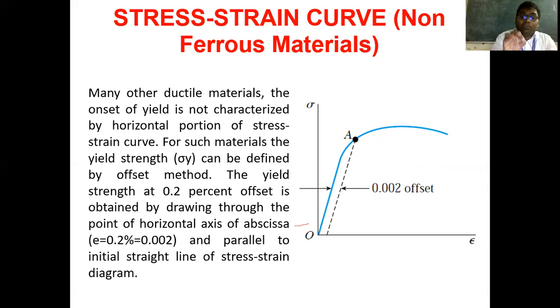All the designs we make for any kind of machinery or element consider the yield stress, so the yield point is very important. What the 0.2% offset method says is: take the amount of strain developed here and multiply by 0.2%, that is 0.002. Suppose the strain is 0.01 and you multiply, then see what value comes. You measure it here and draw a line parallel to this initial line where it cuts the curve. This point can be represented as the yield point of this particular material.